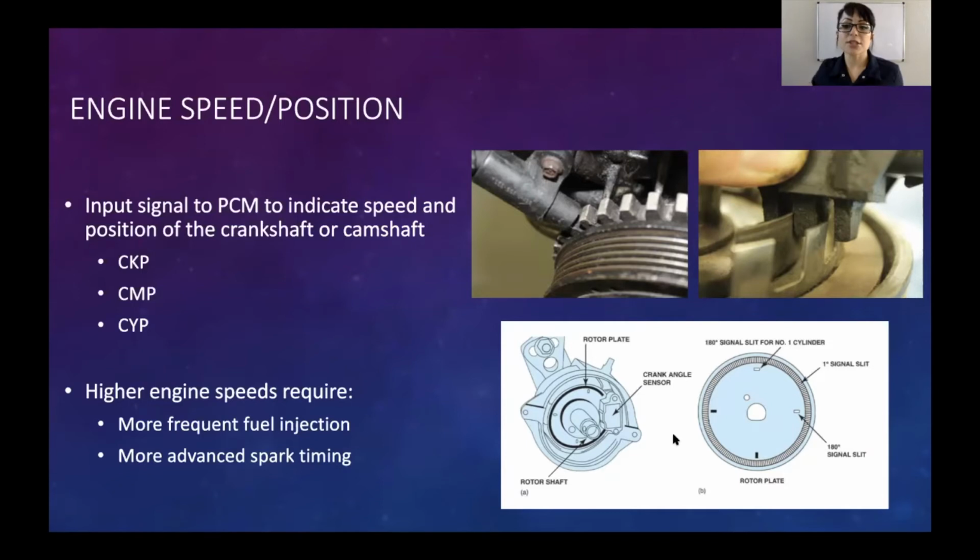Your optical sensor does the same thing, but instead of using magnetic fields through windows or through plates, like how this reluctor wheel is here, it's still essentially like a reluctor wheel, except it doesn't have teeth. It's got little windows, kind of like those little round picture pieces you'd set in a toy as a kid, and you'd click through it and it would rotate and change different pictures depending on the light showing through.